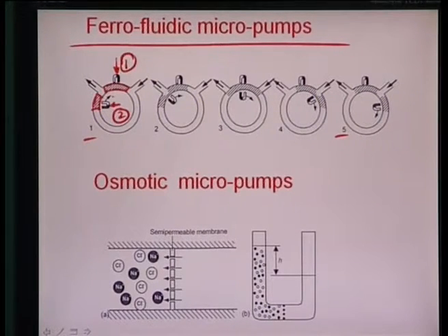So, we move the magnet 2 further in the clockwise sense. As the magnet moves, it drives this ferrofluidic plug along with it, and here it touches this system, becomes one integral piece, and blocks this port. Mind you, this is blocking this port. In the next illustration, as the magnet is moved further, it changes position and goes here. This is a fixed magnet, it is not moving. The variable magnet moves the other portion of the plug away from this static plug, which has been formed.